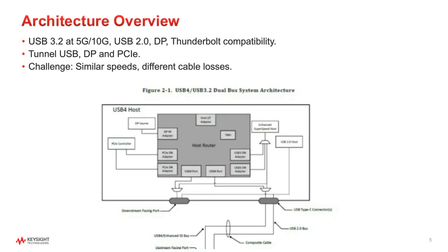It's the host silicon that comes directly out to the Type-C port. So that's one mode. If you look at the right side of the slide, there's a block diagram that says USB 2. I think it says USB 2 host. That's the host silicon. It also is native. It comes out of the Type-C connector in native mode.